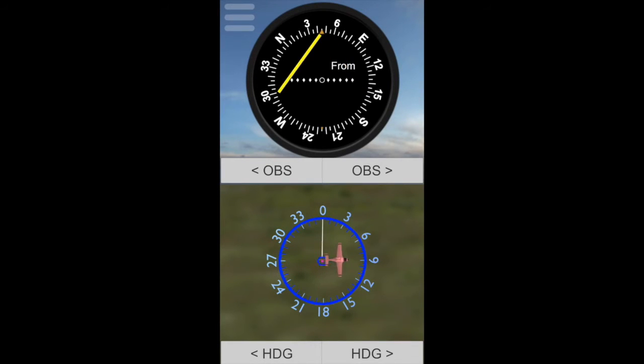And now I'm flying on the 090 outbound. Again, see? So I came from here, 270 inbound. Once I pass over the VOR station, I am flying 090 outbound.